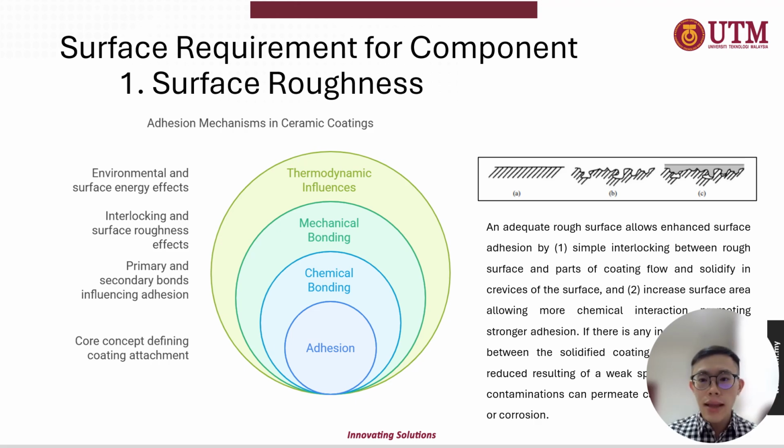If we look at portion C here, in the worst case, if there is any incomplete filling or gap between the solidified coating and the contact area, it will result in a weak spot where water and contamination can permeate into this cavity and cause erosion, corrosion, or delamination.